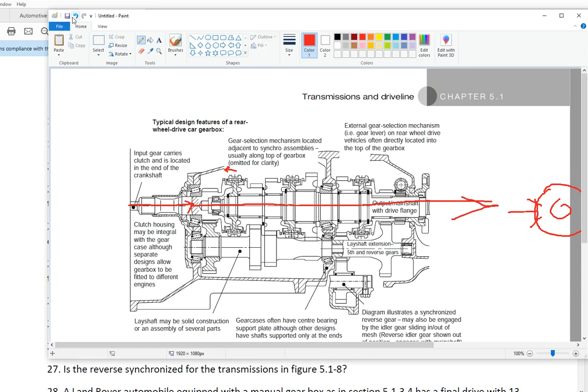how reverse gears are achieved. So for this transmission, reverse gear is synchronized, and you get it with the same synchromesh as for the overdrive. So to engage the reverse, I move this synchronizer sleeve, and I make the shaft in this gear a single rotating unit.